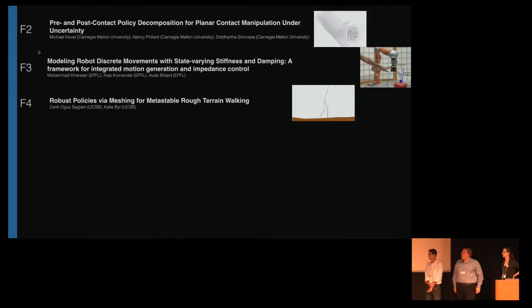Hi, I have a question for F4. In your model, what did you use as control inputs? Were those torque inputs at the joints or straight angular velocity inputs? Those are torque inputs at the joints. So the low-level controller has reference trajectories that it's trying to match. We use a sliding mode control so that we get finite time convergence for those. It's a really interesting question how we design the low-level controllers. I tried to design it to tell you intuitively. We're trying to lean forward a certain amount, leaning forward more, going uphill. It's torque inputs at the end of the day.